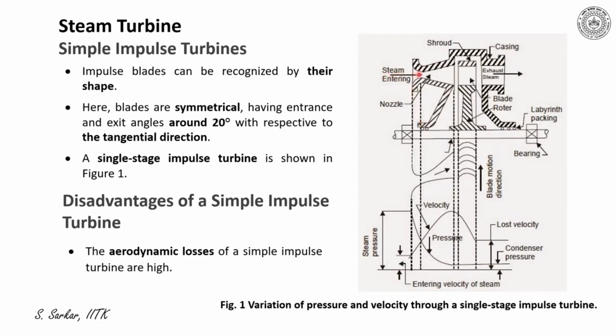First, steam will enter the nozzle and be expanded in the convergent-divergent nozzles. After the nozzle, the rotor follows. The rotors are mounted on the rotor disc, and the rotor disc is in turn connected to the rotating shaft. After the rotor, steam will be exhausted through the exhaust port.